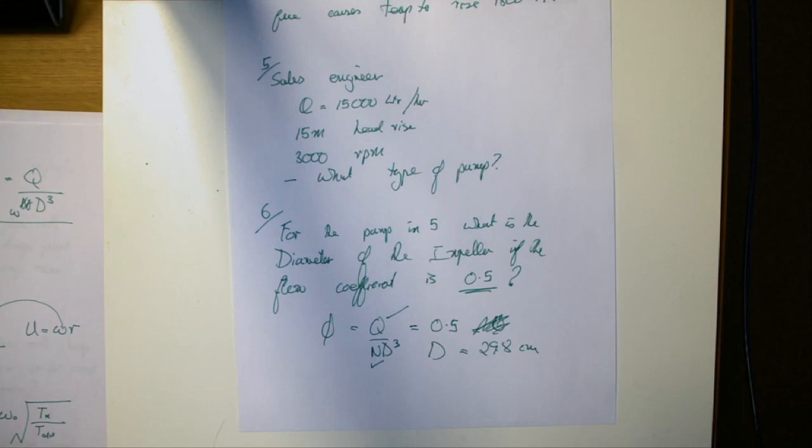What was going on was the pumps didn't really generate enough head according to what the customer had asked for. But the sales engineer was of the opinion that the customer didn't really need that head anyway. So the pumps were made and put in pump test at Mather and Platt in Manchester in a line across the floor, each pump being connected to the next pump with a pressure gauge. So you have 6 pumps in a line with pipes between them and 7 pressure gauges before and after each pump.